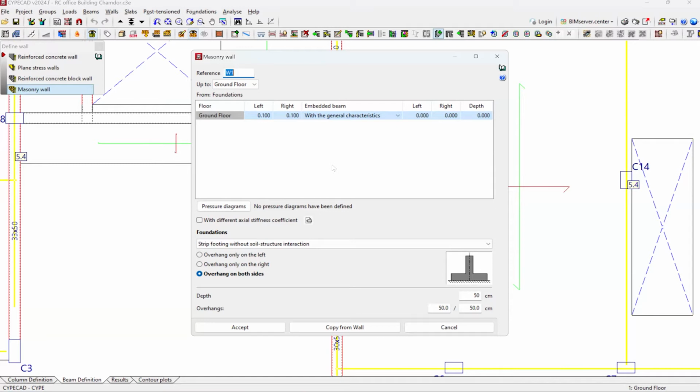It is normally practiced in South Africa that you would find a building that doesn't have a column at all. It's just brickwork. They do foundation brickwork, then straight to the slab. So with CYPE software, you are able to do the same type of design or construction method by just introducing the masonry wall and putting in the type of slab that you are considering to use, then you design, and it takes the design appropriately.